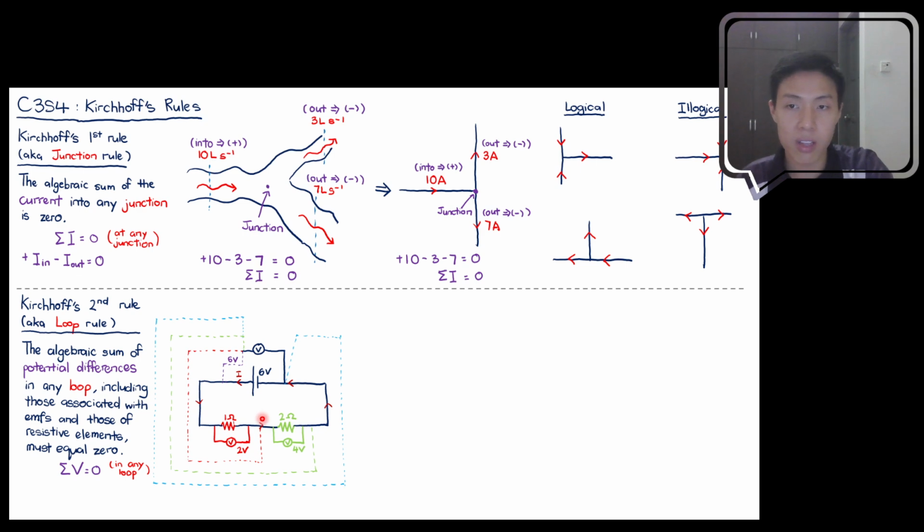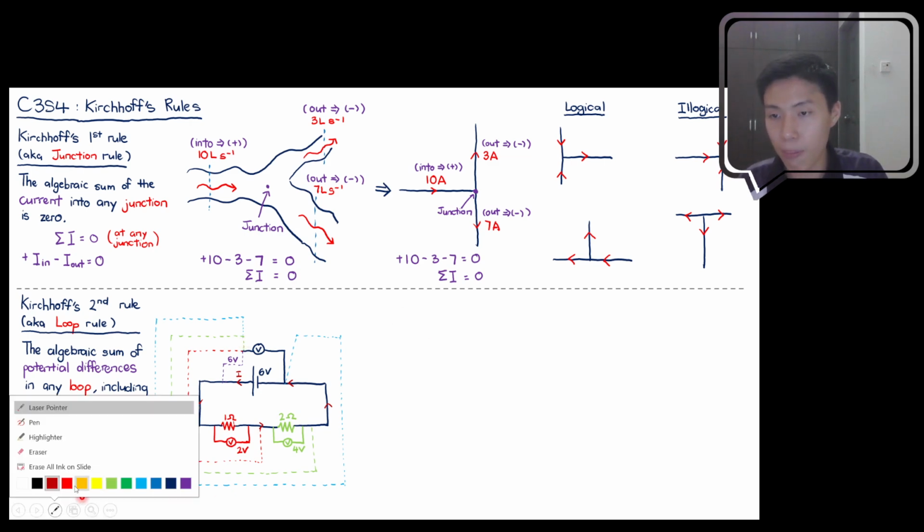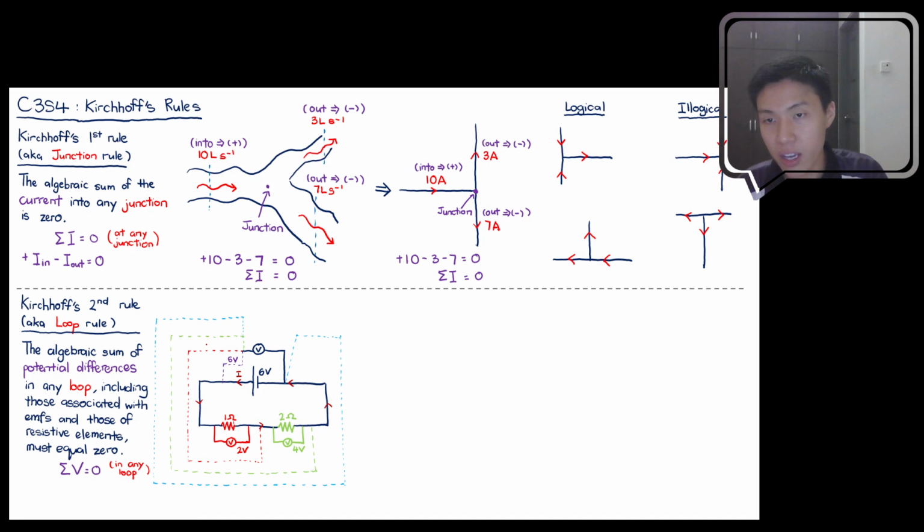So in thinking about it in terms of per coulomb of charge, now we can say that in terms of voltage, for this red path over here, you initially have a gain of plus 6, but now you lose 2 due to the resistor, then you end up with only 4 volt. That's what you can see. Okay, then now if you continue on your journey over here, where you move along the current path past the 2 ohm resistor, then now a similar thing will happen.